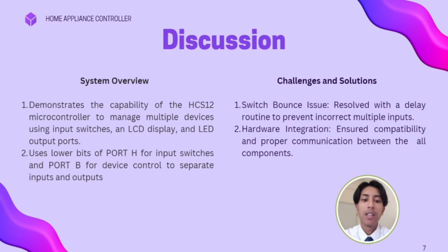Next, we got our challenges and solutions throughout the making of this project. The first challenge we met is the switch bounce issue. Switch bounce is when a mechanical switch is pressed or released, its contacts bounce momentarily, causing multiple rapid on-off switch signals. To resolve this problem, we use a delay routine to prevent incorrect multiple inputs.